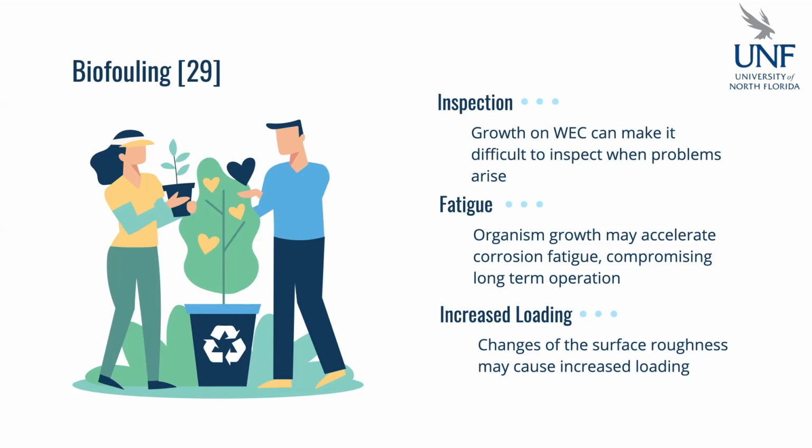The next thing is fatigue. If we have organisms growing on a WEC, they're going to be carrying out chemical processes right on the WEC surface, potentially causing the materials to corrode. And that's on top of the corrosion from the salt water that we were talking about before. All this corrosion could potentially lower the fatigue life of the device.